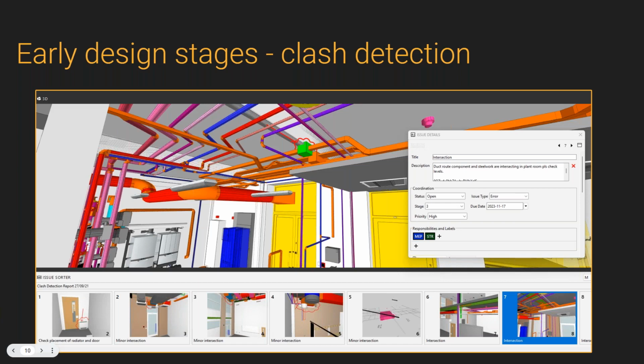To give you an example of that, I remember being in one meeting where they needed to check the cable routes, so that's wall trunking, and wall fixed audio-visual equipment wasn't clashing. That was something we could build a simple rule set for in Solibri, but it wasn't something my big clash detection rule set specifically looked for. So being quite agile and reactive in how we're seeking and addressing clashes is crucial, and it has benefit to a lot of people.